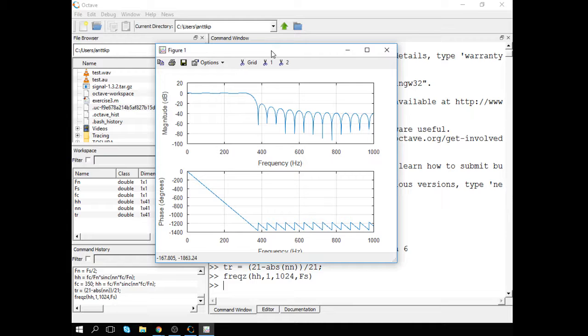That actually worked surprisingly well. So I estimated my transition bandwidth originally was 250, and now I put there 5 times more width for the filter. So basically now it's down to about 50 Hertz. Yeah, so it works just fine.